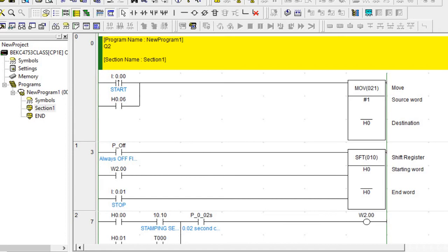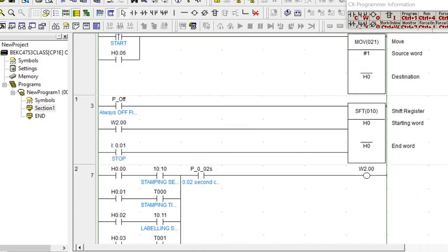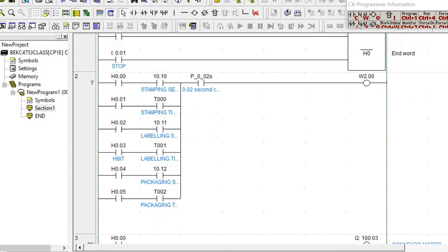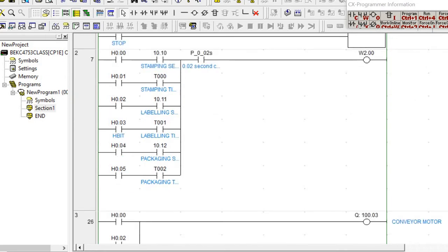Okay, so to make sure the bit is loaded here, it's important to put a hash in front of 1, because with the hash we are declaring this as a BCD. So this is a 1 number instead of a hex number. Then, like I said, when we declare the steps, we know that the flow itself starts with the conveyor moving and then stop.